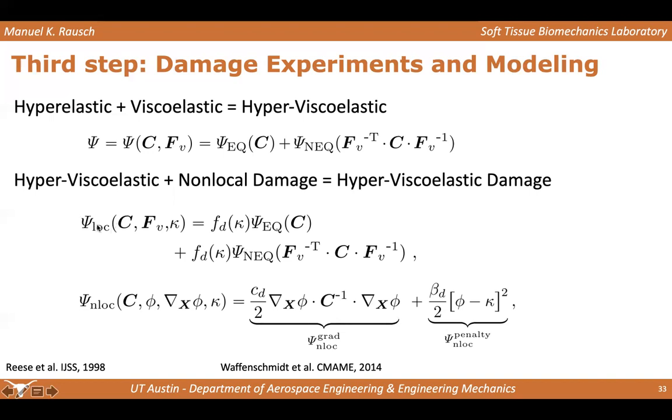But that is what happens on a local level. And this is where a lot of the damage formulations stop. The issue with that is if you store damage only on a local level, then your damage fields ultimately become a function of your discretization. And so we essentially see non-convergent behavior in these damage formulations. And I'll show you this in a second.